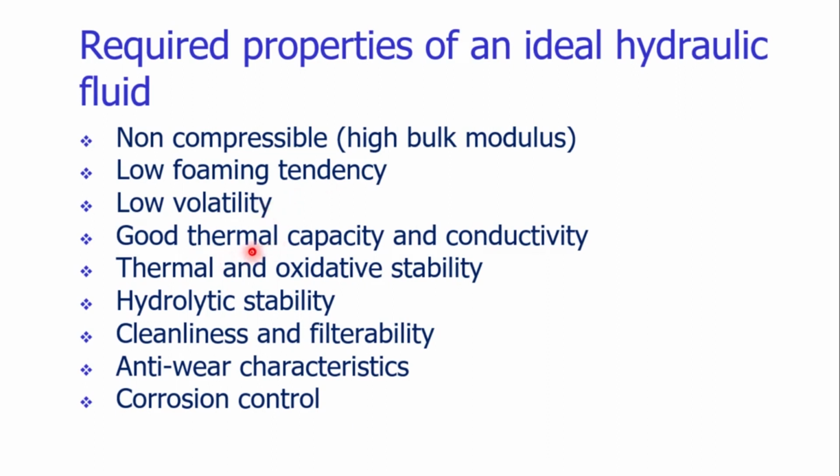The ideal hydraulic fluid should have very good thermal capacity. The heat capacity should be high, and it should have good thermal conductivity. If the conductivity is low, it will get heated up, and that hot hydraulic fluid will lead to the failure of the system. It will damage the system. The hydraulic fluid should have sufficient thermal and oxidative stability. The fluid should be stable enough. It should have hydrolytic stability as well.